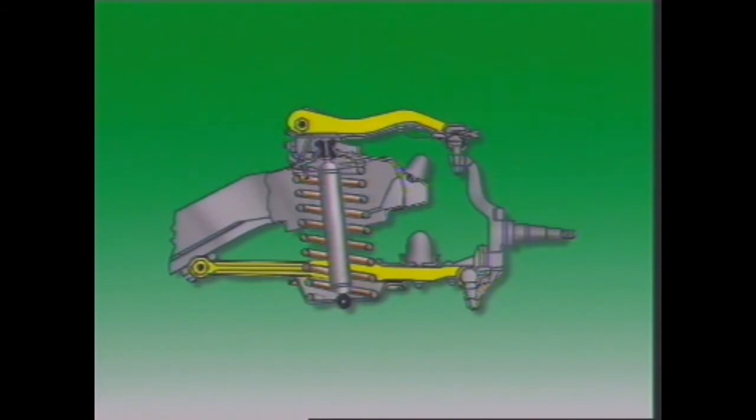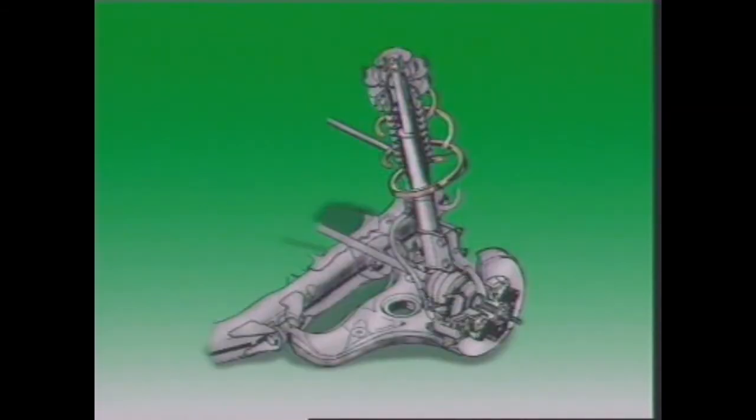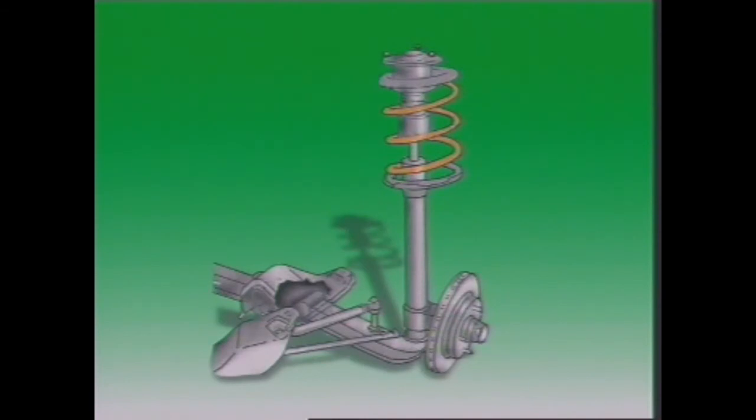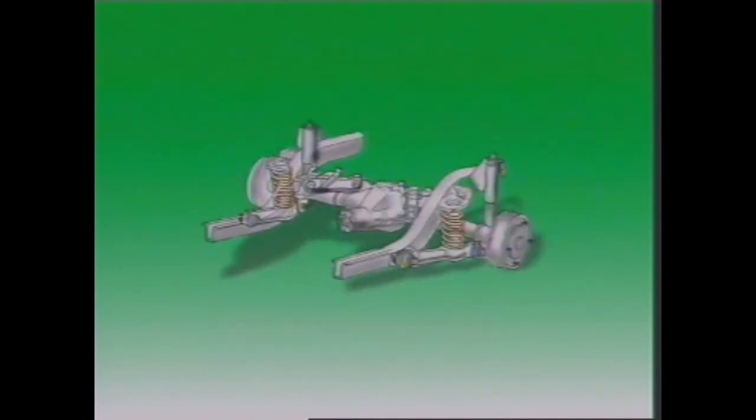Parallel link front suspensions have 2 control arms. Vehicles with strut-type front suspension have only 1 arm. It can be a wishbone shape with 2 fulcrum mounting points or straight with single fulcrum. The inner end of the control arm is pushed to the vehicle body, and the outer end uses a ball joint to allow changes in the steering angle for turning. This rear-wheel drive vehicle has coil springs in the rear suspension. Therefore, special provision must be made to locate the axle laterally and longitudinally.